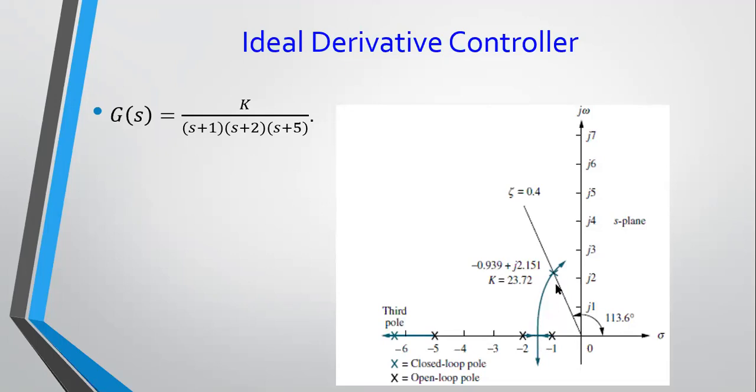So you have a breakaway point here, and you can see this is going to be a dominant pole, but for these poles on the left hand side, the further this is to the left, the better your second order approximation is going to be. Okay, so let's say in this case, since we're dealing with transient, we want to operate along this damping ratio line, which we have put as 0.4. We know that this damping ratio is going to lead to a percentage overshoot.